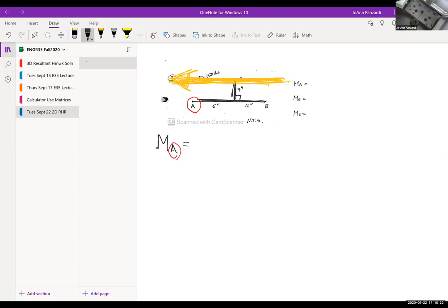Okay. Correct. So let's set this up. We're trying to find the moment about point A. It's the absolute value of the force, which is 150, times the absolute value of the perpendicular distance. This 7 inches here is also here. This is 7 inches, because you could put a string on it. A string on it for what? Try to look at a spin? Let me just keep going, Jason. I want to get the mechanics first, and then we can talk more about the physical.